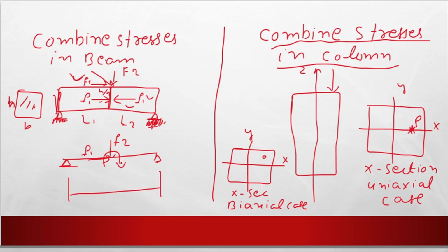And now, due to the axial force, by using basic structure analysis, you can draw its shear force and bending moment diagram. It may be like this one, because there is a point moment, either this point will go up or down, and then this will be the bending moment diagram. So at any section you can use the value of M.